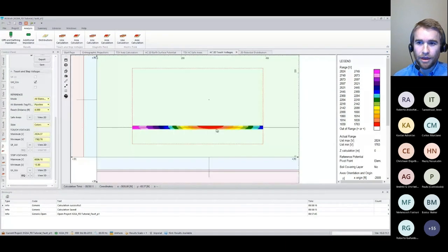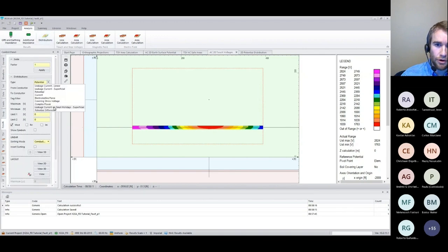So we have a point next to the transmission line where we're elevating the soil voltage due to the conduction from that tower, which is actually reducing the voltage difference between this pipeline and the soil. And that's, of course, going to correlate to our coating stress as well.